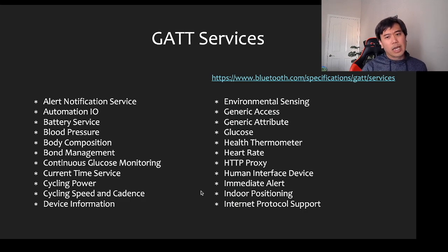So there's different types of predefined GATT services. One of the most common ones is the battery service. It's kind of like a pattern that some device manufacturers implement, so the client, the one that's trying to connect to it, would at least understand and have common communication values. But lots of devices depend on what they implement. They may implement something custom.